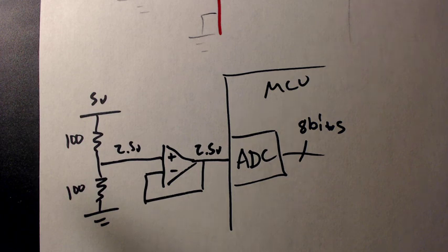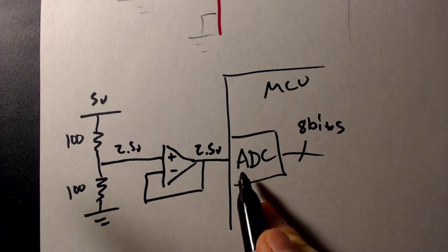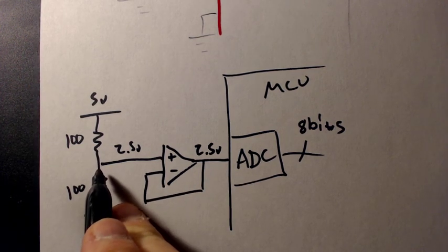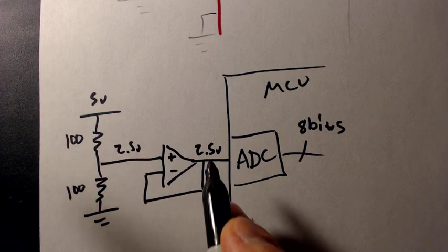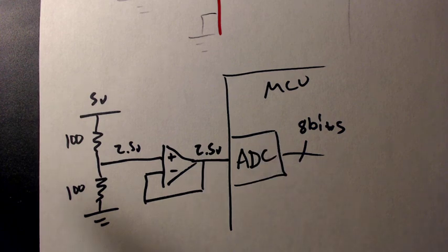So that's where the voltage follower shines. It's for fixing the problems created by bad impedances, right? Golden rule of impedance: always drive a high impedance input with a low impedance output. This is high enough that it doesn't matter what we connect here, and this is low enough that it doesn't matter what we connect here. Okay? So that goes ahead and covers this circuit.